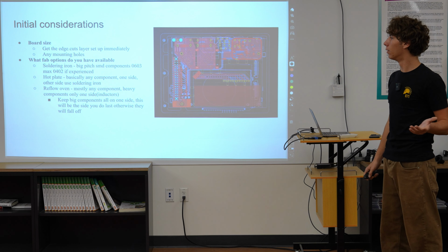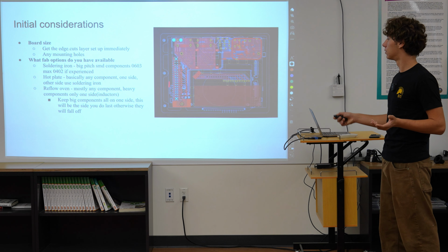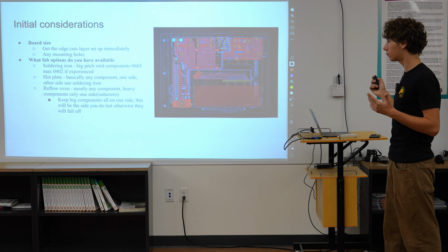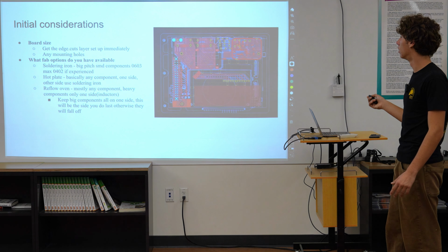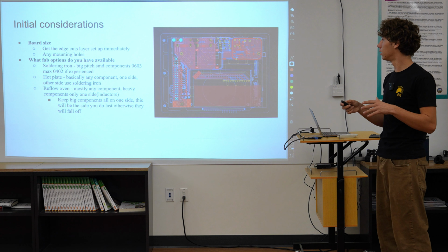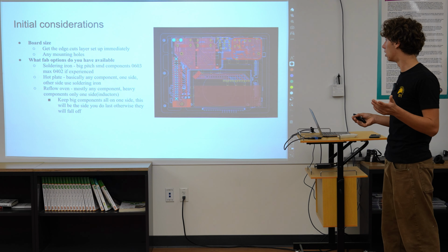So if we didn't know that, or if we didn't do that first, this whole design would have been kind of skewed. Also, we had this 40-pin header here. Just all of that stuff plays a lot into your design. Otherwise, we would have probably put the power regulation right here or something like that. But just having the edge cuts set up immediately, you can make obviously small tweaks later on.